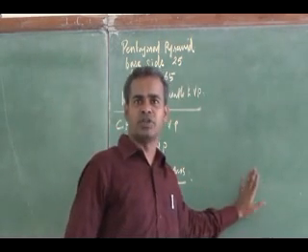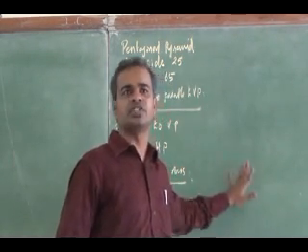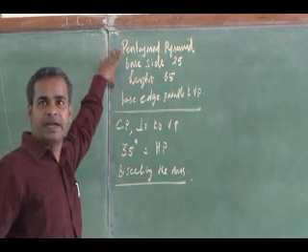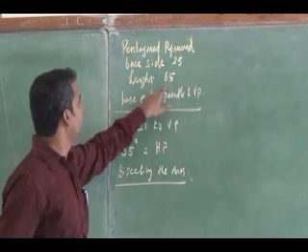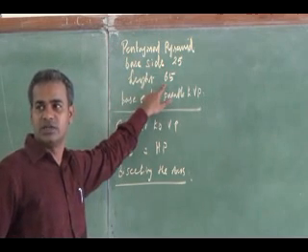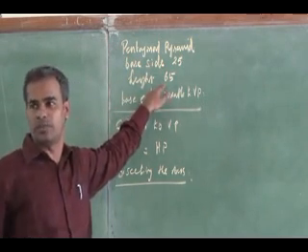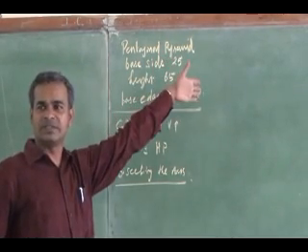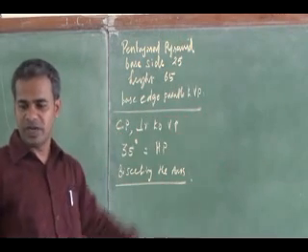Straight away you draw the projection. Make it fast. Draw the projection of this pentagonal pyramid of side 25 and height 65. Yes, side is parallel to VP. Okay. Draw the top view. Draw the front view. So represent the cutting plane. Mark the cutting points. Make it fast.